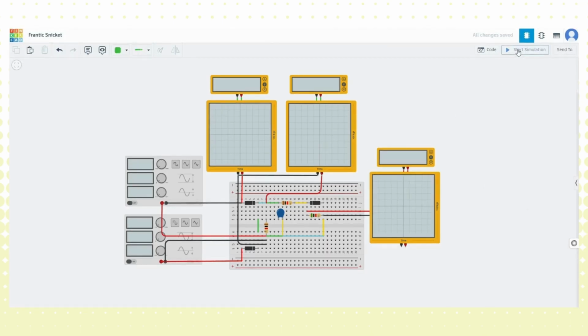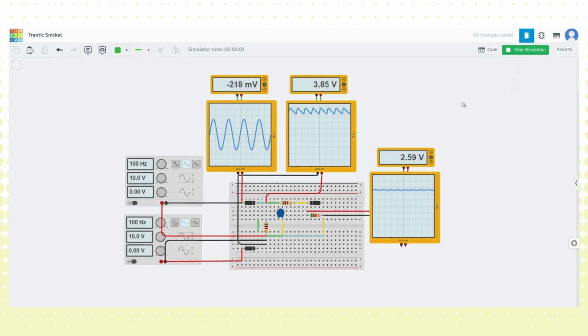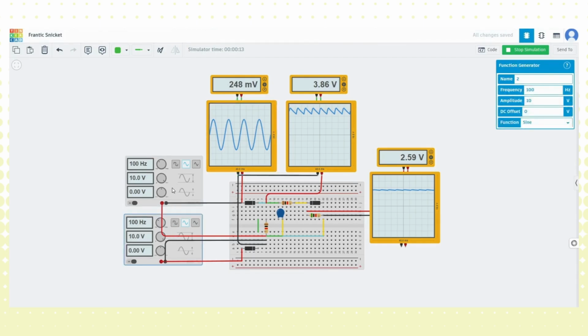Next is the simulation part. I also will explain the flow of it. Firstly, from the multimeter and oscilloscope, we can observe the input from the power source. We will see it is an alternating current AC voltage. Look, positive, negative, and then from this power source, during the positive half cycle of the voltage on the transformer secondary winding, the current will flow through this diode 1. This is because at that moment diode 1 is in forward bias, while diode 2 is in reverse bias. So hardly any current will flow through diode 2, and it mainly goes through diode 1. This is what we call rectification, turning AC into DC voltage.